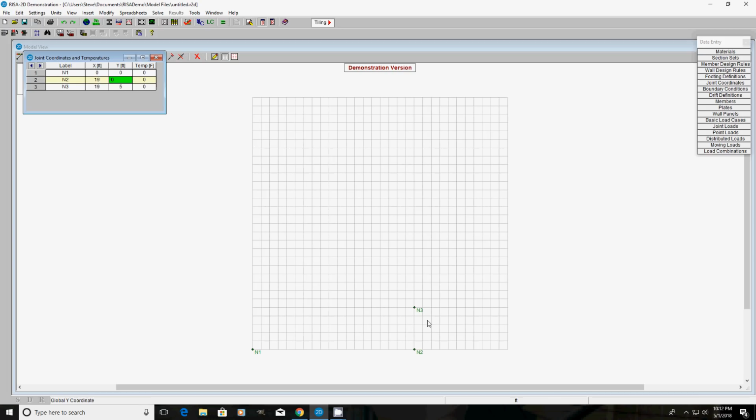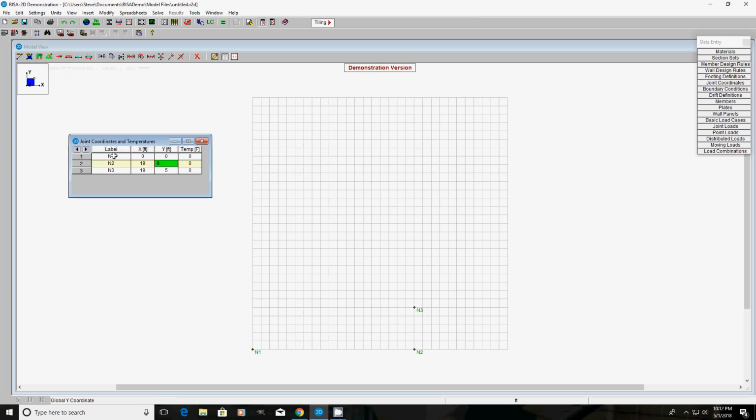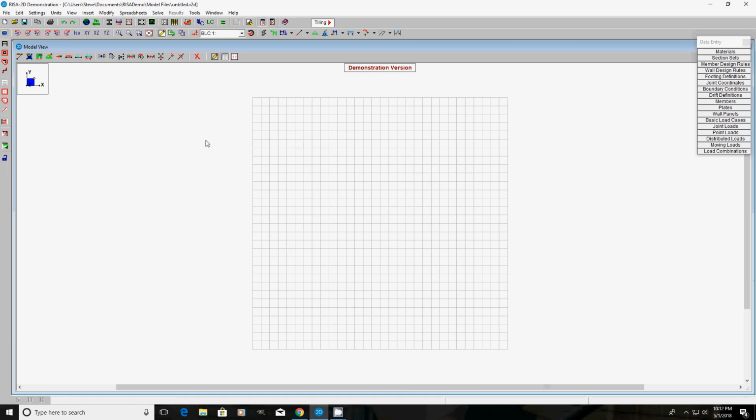So what I like to do is anything with any type of angles or curves, I'll bring that in with a DXF file. So let's go back up to here. Now, if you're ever in one of these spreadsheets and you want to delete, you can simply just hit F4. So we'll hit F4, F4, F4, and that just deletes all those. So I can X out of that.